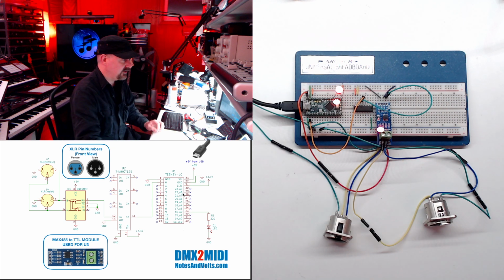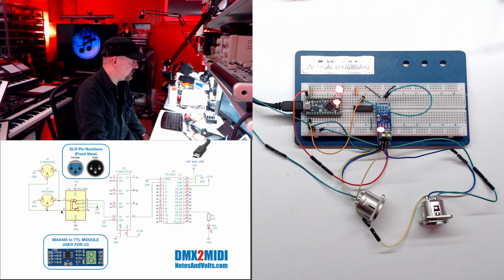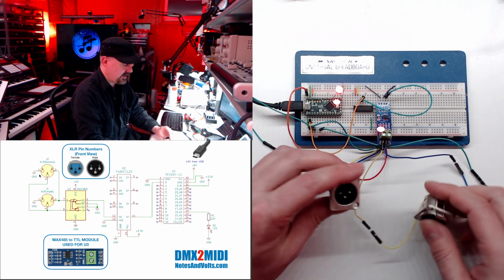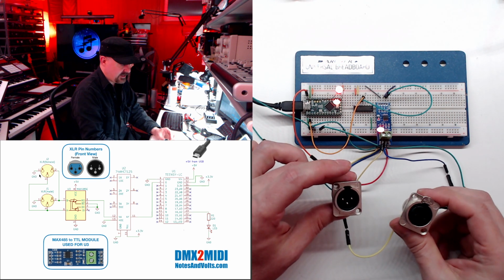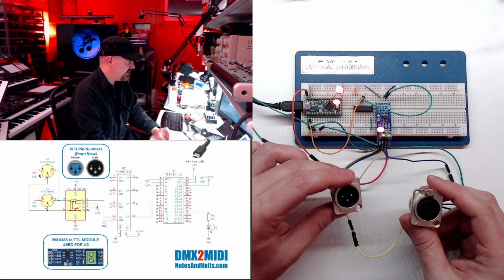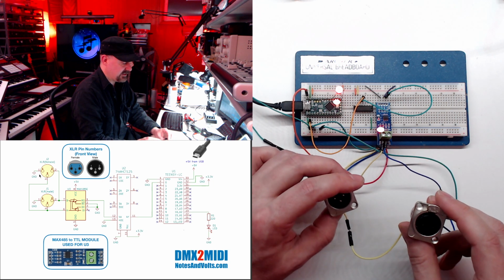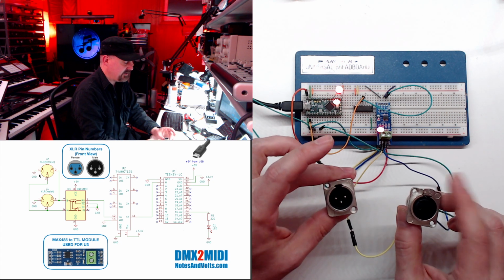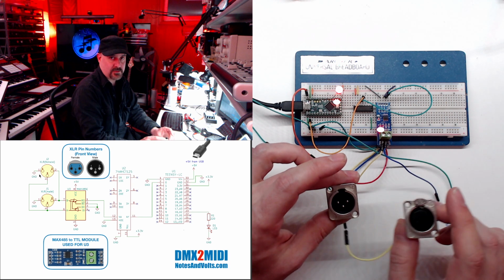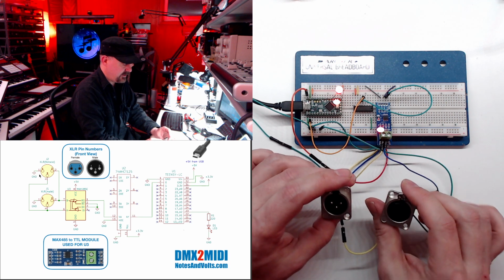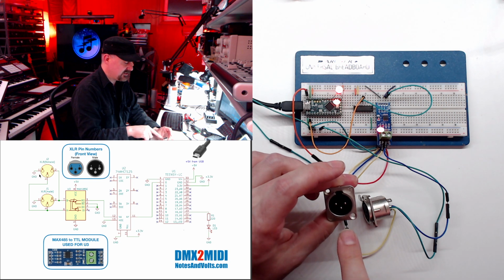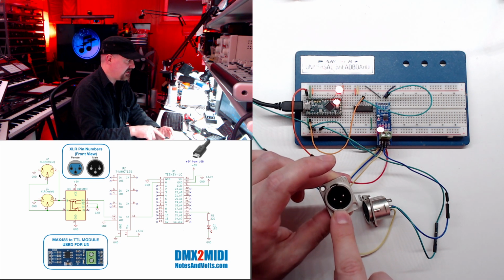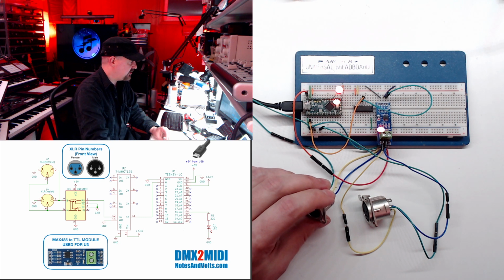Okay, so now let's take a look at the circuit from the input to the output. So at the start of our circuit, we've got these 2 XLR type jacks. Now DMX can either use these 3-pin jacks, or it also comes in a 5-pin version. And you can use either one with this circuit. If you use the 5-pin jacks, just make sure you look up the pin numbers and wire them accordingly. So we'll attach the cable from our DMX controller into this jack here, and that's going to go to the input section of our MAX485 module.